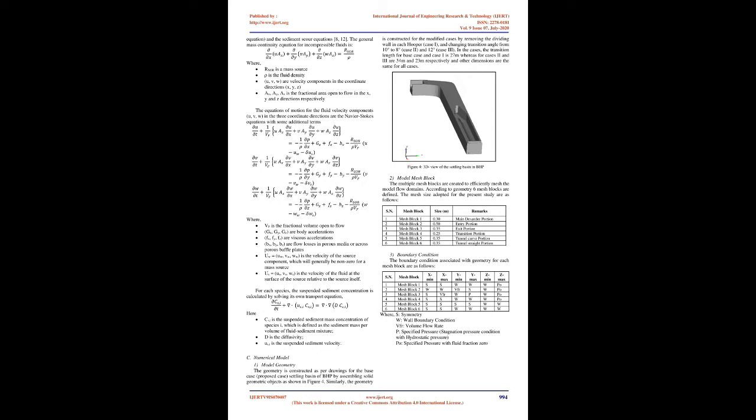The settling basin, a 90 m long desilting chamber, is proposed to remove suspended particles of 0.20 mm. A basin has 2 chambers, each having a flushing channel with bottom width 1 m and a transverse slope of 1:1 on both sides. The plan of the conveyance system and the cross-sectional view of the settling basin are shown in Figure 2 and Figure 3 respectively.